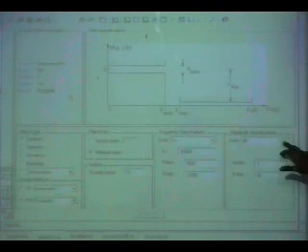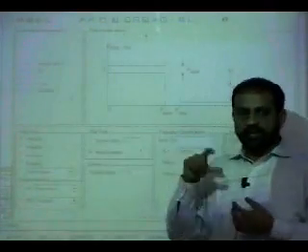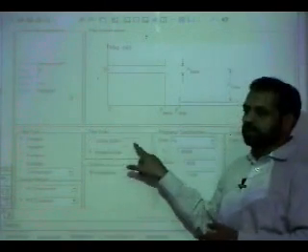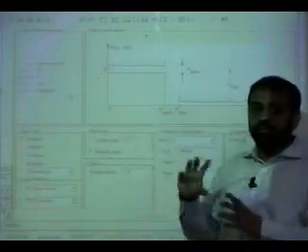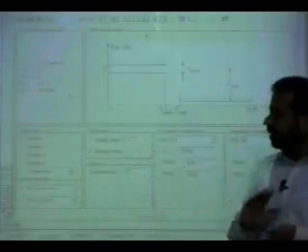If you want to specify them in magnitude, you can do that too from here. And then if you want to specify an order, you say, no, I only want a 10th order filter. You click this, specify order. If you want MATLAB to give you the best design, let MATLAB do it for you. You say minimum order. Okay.